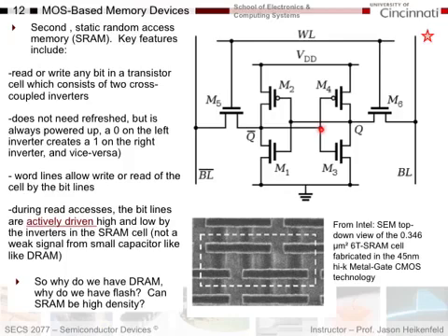And the beauty of this, and why this works well, is that if I set this up to the state where I have a 1 here, well, a 1 goes through an inverter and becomes a 0, right? A 0 goes into this inverter and becomes a 1, which reinforces the original 1. And so once you lock this into a state of a 1 or a 0 on one inverter, the other inverter reinforces that.